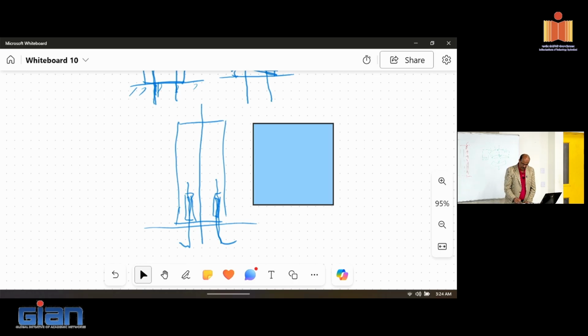So basically you have this piece, and there are a number of ways to build this one. It's a typical couple of things, except that we debond part of the rebar. The reason we debond is you don't want that strain to build up.